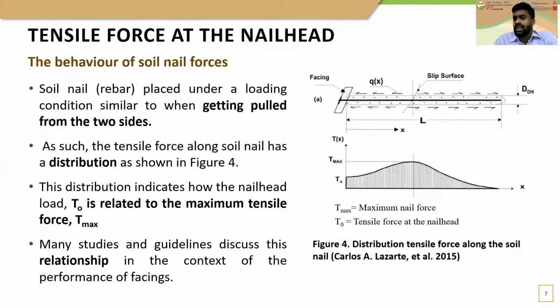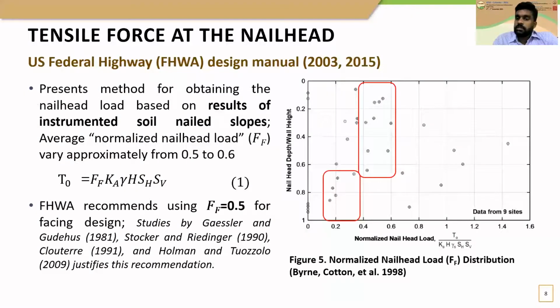Moving on to the design of facing, the tensile force at the nail head will be discussed first. When the slip surface forms, the tensile force along the nail takes a distribution as shown in figure 4. This distribution shows how the nail head load T0 is related to the maximum nail force Tmax. Next, some of the design guides available for evaluating nail head load will be discussed.